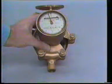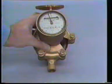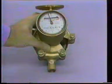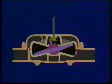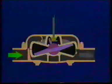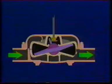This type of instrument is frequently used to measure amounts of fluid delivered. A common application is a water meter for residences or businesses. Let's take a look at an illustration of the nutating disc flow meter to see how it measures flow. The meter consists of a housing that contains the nutating disc. The inlet and the outlet of the housing is usually marked. A counter drive pin is attached to the center of the disc.